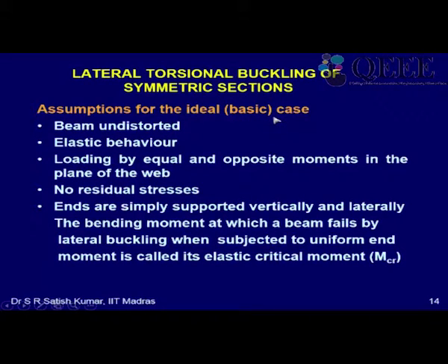So if I take this, I want to know at what bending moment M critical this beam will laterally buckle. If it's an ideal case, we say that the beam is undistorted, then it is under elastic conditions. So there is no inelasticity we are assuming anywhere to occur. Then loading is by equal and opposite moments in the plane of the web.